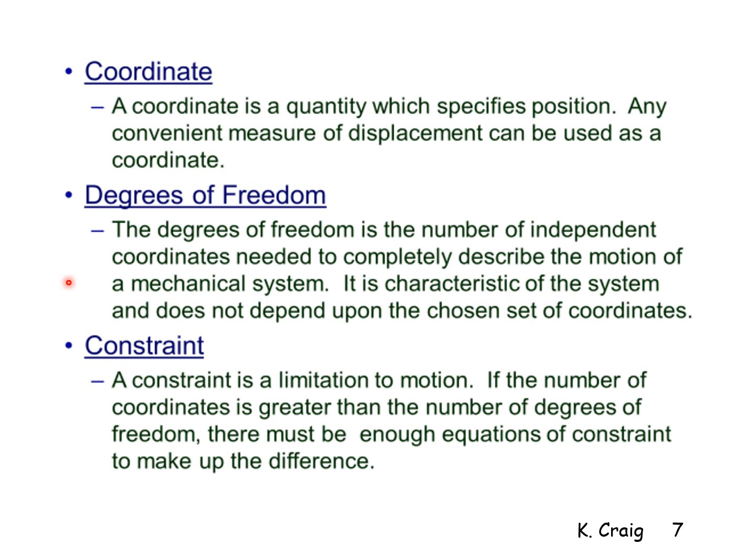If it moves on a curve in a plane, it has 2 degrees of freedom, x and y, if it translates in curvilinear motion. If it moves on a plane where it can translate in any direction, but can also rotate about the z-axis perpendicular to that plane, it has 3 degrees of freedom, an x, a y, and a theta.